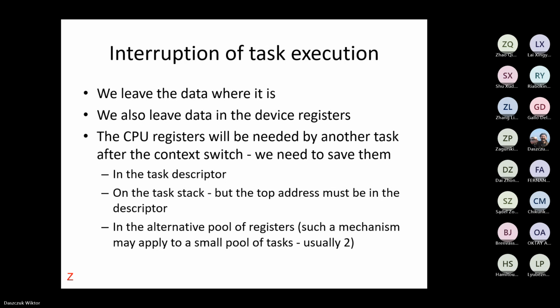3 places for storing registers are used. In some IoT processors, there is a second set of registers. So one set of registers for user state and one for system state. And if we have only one task, which is quite typical in IoT, then we simply switch between system and user without storing the context.